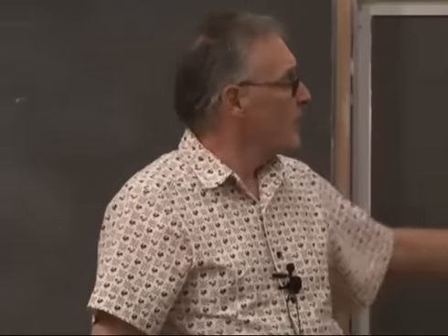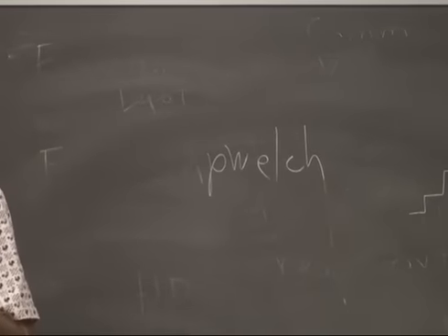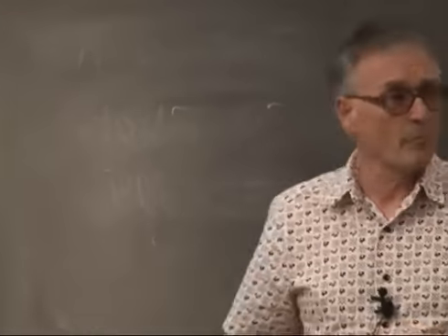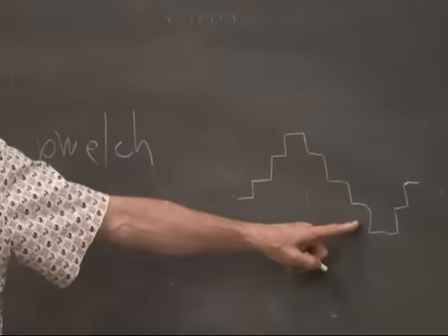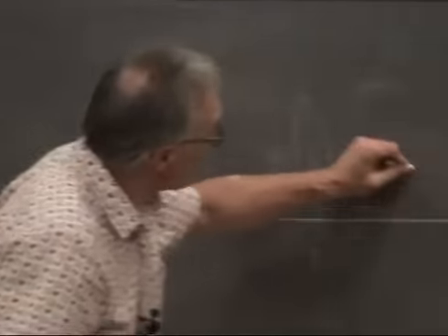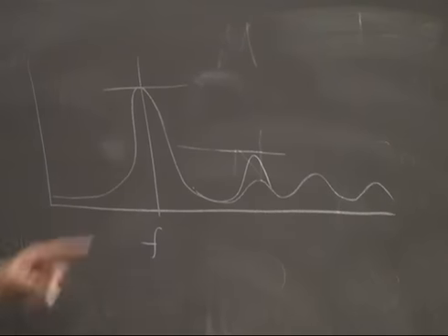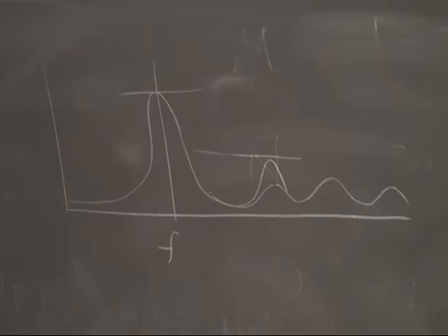What do you know? pwelch has the advantage of doing some averaging and some shaping of the spectrum, so you get a more accurate example. So you could just try different numbers of samples, FFT them using pwelch, and measure the ratio of the next highest error harmonic to the harmonic you think you're synthesizing.